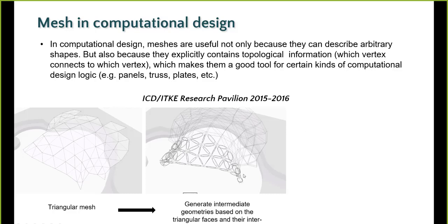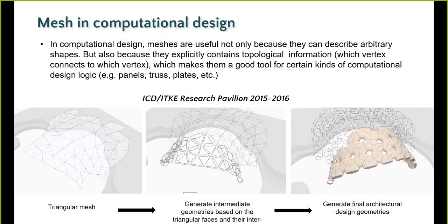So they had this underlying mesh, and they could build some sort of topological model on that, and so they knew what shared edges were, and then they could build more complex geometry from that as a framework, basically. Through the mesh, they could generate surface normals, get shared edges, and generate this geometry.